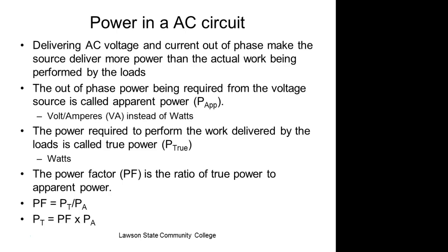Because why? It seems like they would want you to be out of phase because they get more money, but you have to understand their power grid has to handle that phase shift. So they would rather not have a phase shift at all. If you've got a big phase shift, they have to have bigger transformers and big conductors, and it would cost them a lot more to support out-of-phase power than it does to support in-phase power.